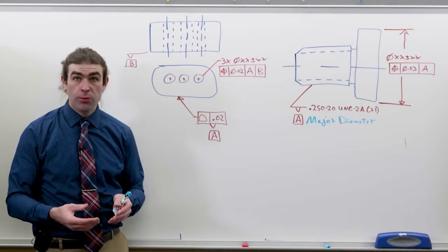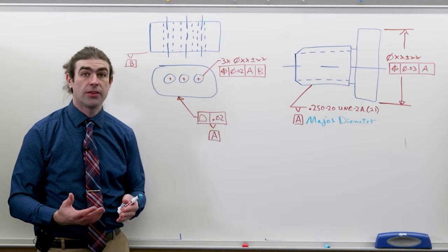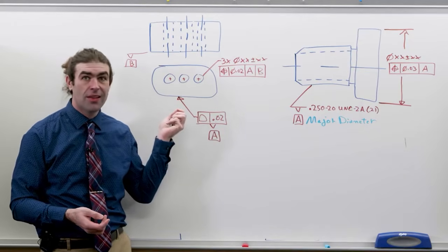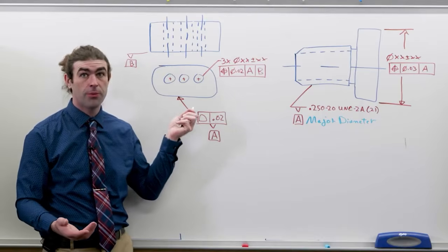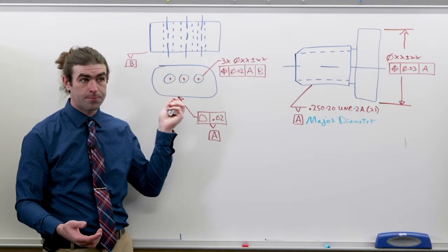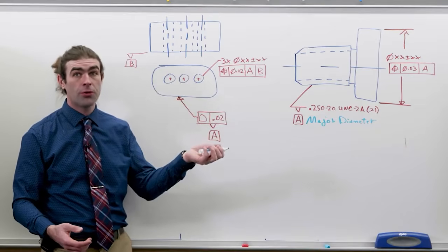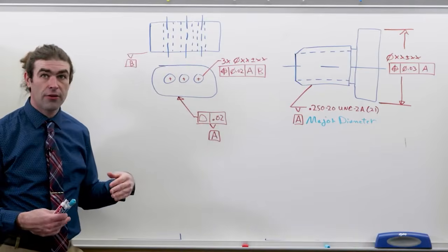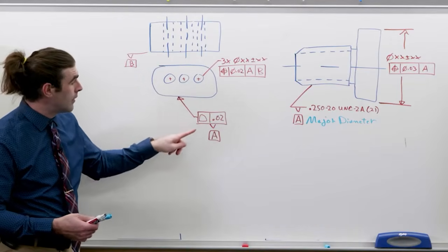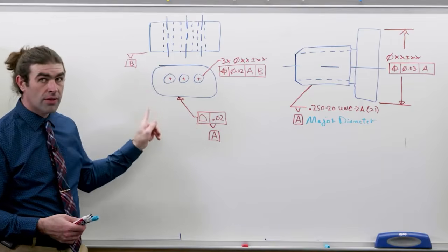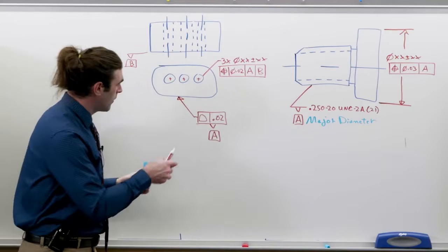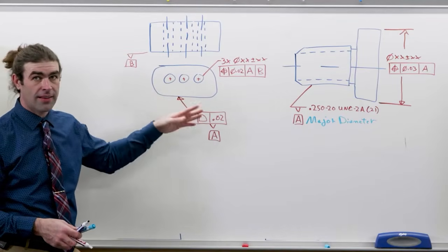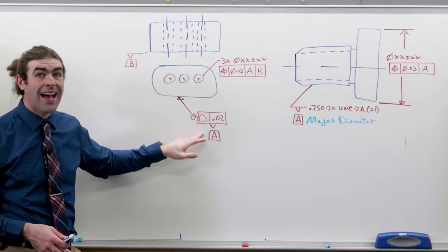So next, you can use profile shapes as a datum. So what I'm talking about are irregular features. So in this case, I've got a slot shape that's an external feature, with 3 holes going through it. You could pick this side or this side to favor and make one of those a datum, or you could tolerance the outside of this with a profile, and I should have an all-around symbol there. Dimension it with basic dimensions. I left that part out, and make that the datum.